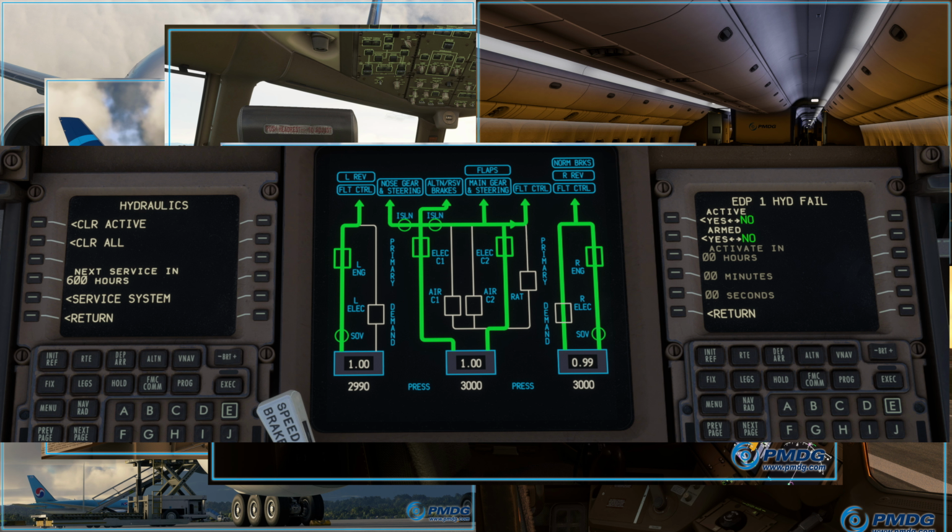function as demand pumps, which are being used, for example, during landing gear extension, retraction, during flap extension, etc., and are, of course, audible in the passenger cabin, as they are located roundabout in the area where the wings are, so when you're sitting in that area you will hear them especially loud in the passenger cabin when they're operating. Likewise, the right-hand system is operated by an engine-driven pump and a demand pump, in case there is a stronger than normal demand on the system.